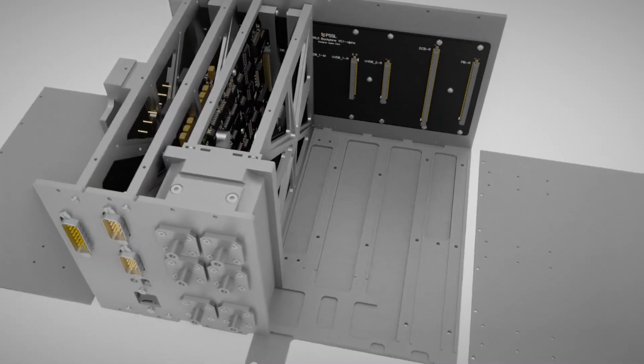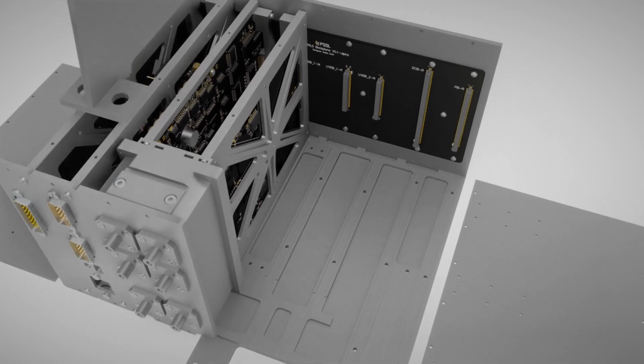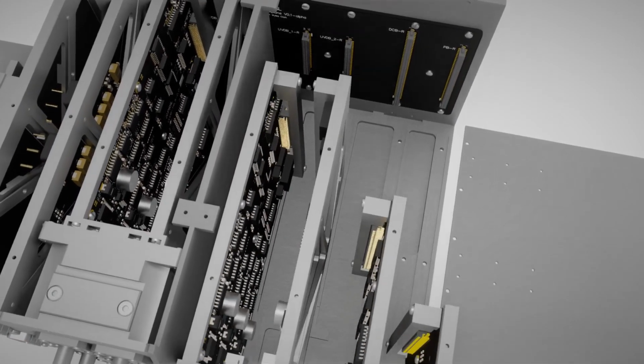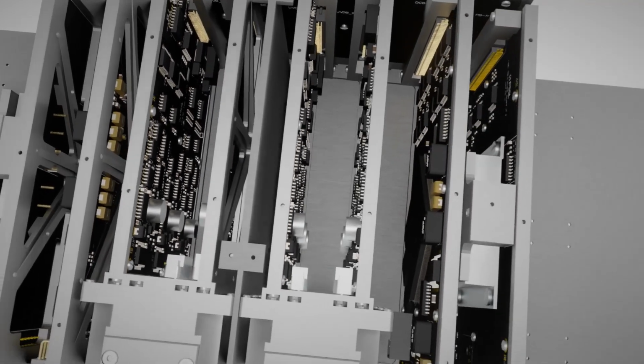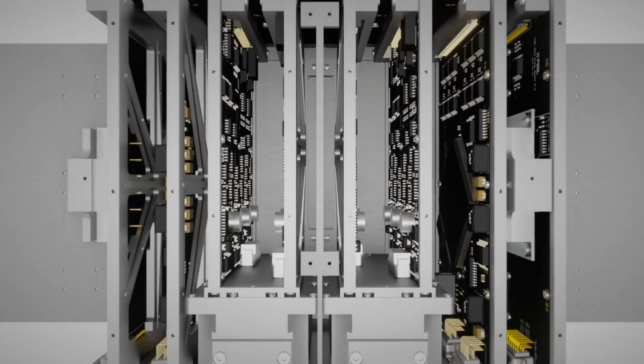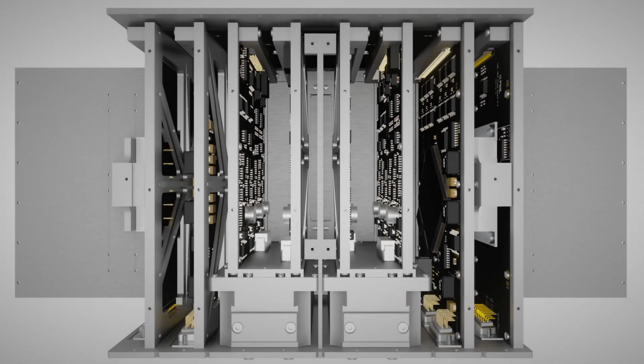Hold on now, what about the other half? Well, after putting the center ribbon to separate the two halves, we can install the fully redundant modules. These are identical copies of the main modules, all connected to the same backplane board. This allows for redundant cross-strapping. For example, each power module can fully power the system in the case of an issue with the other.